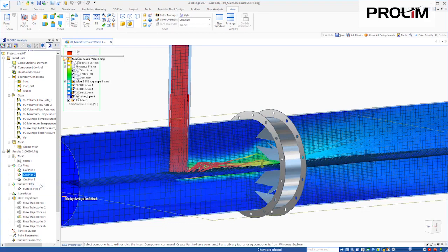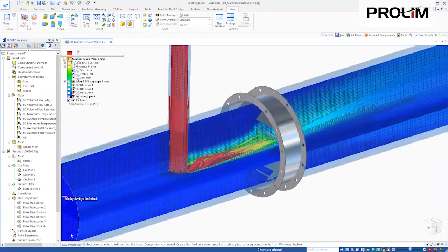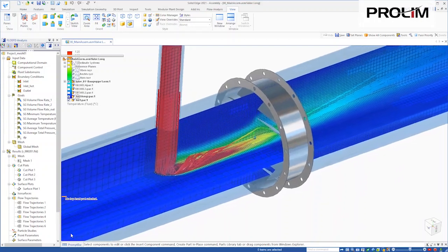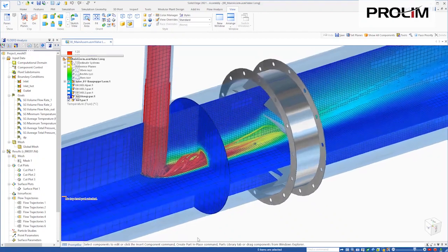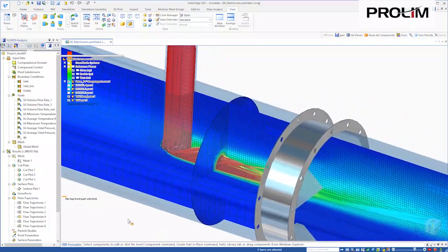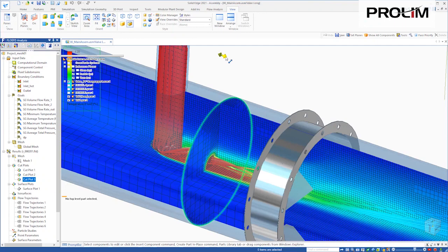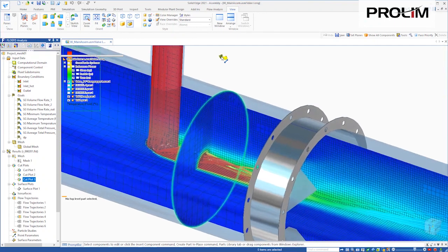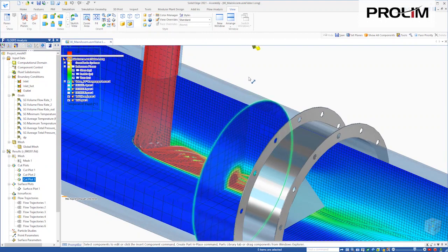Different cut plots show several regions of the results and the refinement. The visualized parameter is temperature. The hot gas is shown red, and we can clearly see the mixing behavior in the larger duct, behind the protruding small pipe and in the damper area. These plots can also be dynamically moved directly in the CAD model, and we can see the refinement in and around the high temperature core flow.